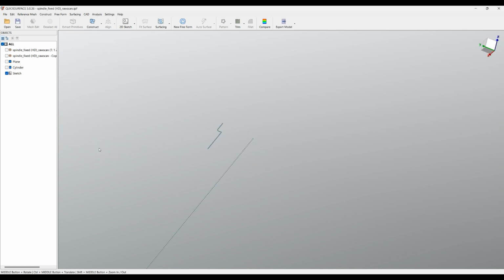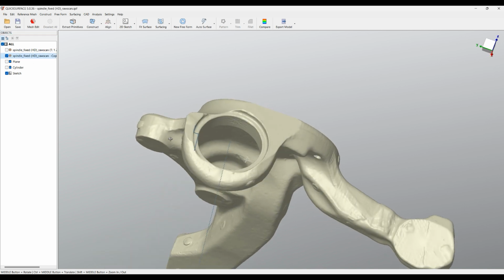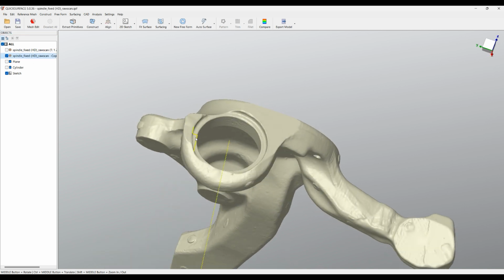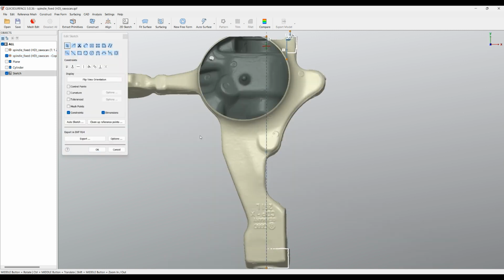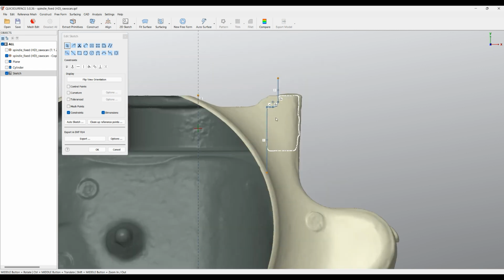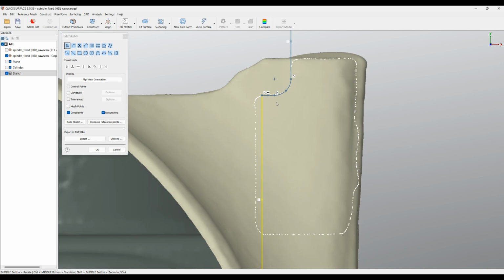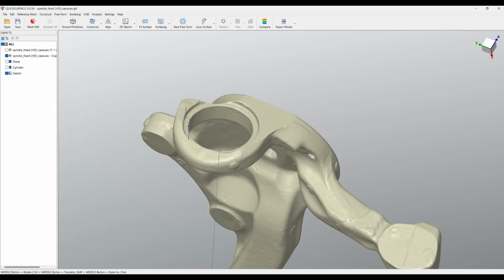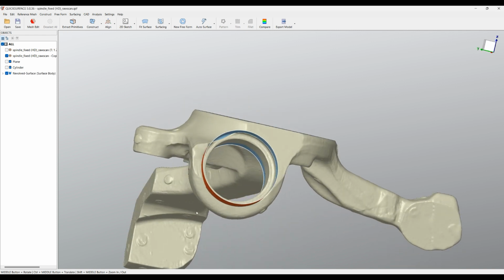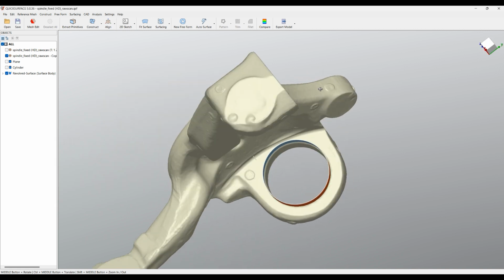The reason for doing this, I'm going to make a revolved surface that will cut through this shape. In fact, in this moment of reconstruction, I need to cut this area from the mesh for the purposes of automatic surfacing. So technically what I'm going to do is just put this inside so we can remove enough material from our mesh, and then I will just select and create this as a revolved surface. So you can see what is the shape here. It's good enough for me.